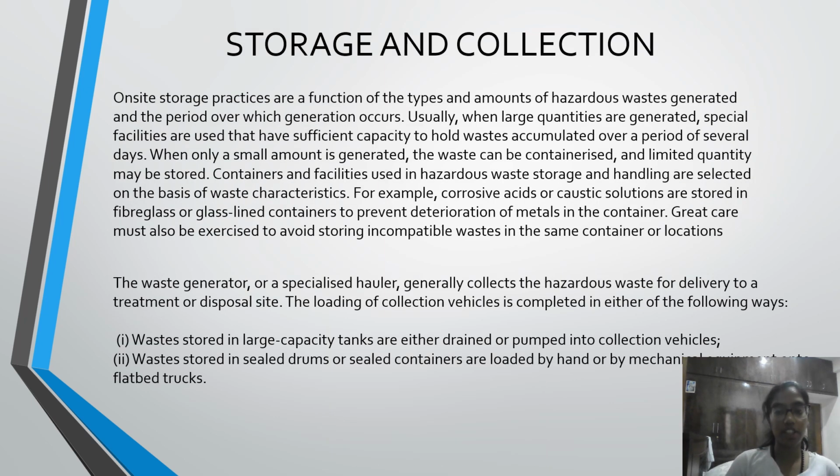Coming to storage and collection, on-site storage practices are a function of the types and amounts of hazardous waste generated and the period over which generation occurs. Usually, when large quantities are generated, special facilities are used and have sufficient capacity to hold waste accumulated over a period of several days, and only a small amount is generated. So, this hazardous waste cannot be kept for a very long time. It can be kept only for a period of a few, 2 to 3 days.